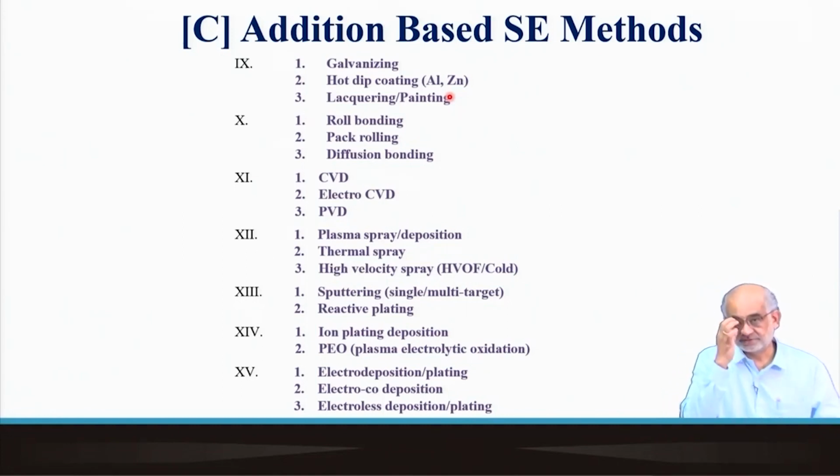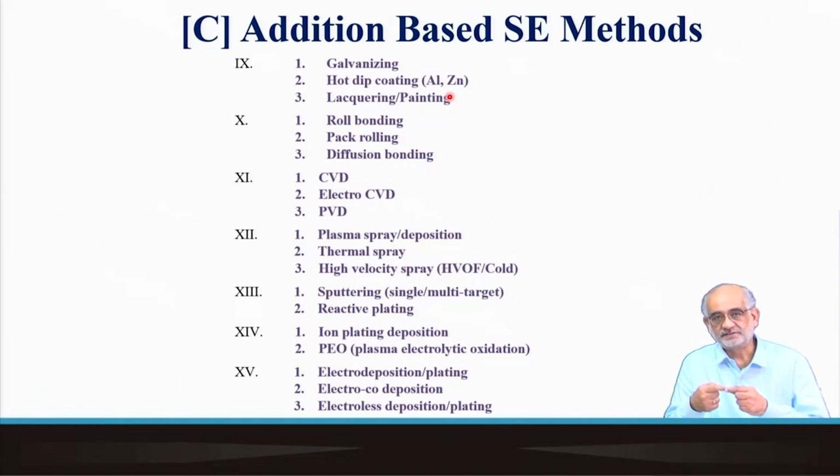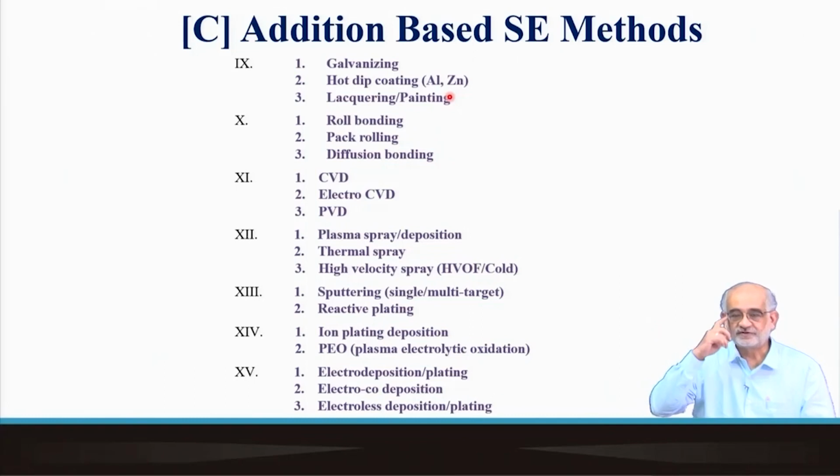with a certain statistically average residence time, during which the molten metal starts dissolving a part of the solid that is passing through, and in the process the zinc also is able to wet the surface well or adhere to the surface well. As soon as the solid, either rod or sheet or wire, is withdrawn from the bath, it undergoes a cooling cycle within which a zinc-rich layer forms on top of the surface.